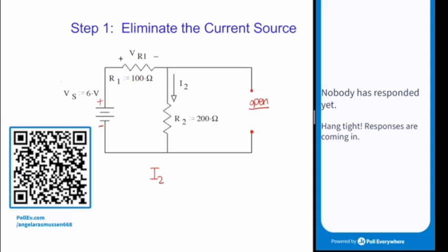What's the circle here? A current source? Yeah. So a current source sets that branch to have that amount of current that it sets. If it's 2 amps, that will set that current branch to be 2 amps, and it doesn't change. It doesn't affect the voltage. It will have a voltage response. Every element has voltage and current. Correct. Yep.